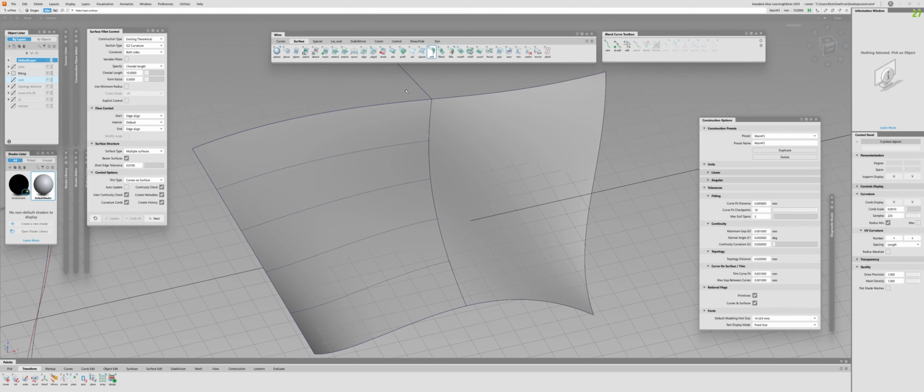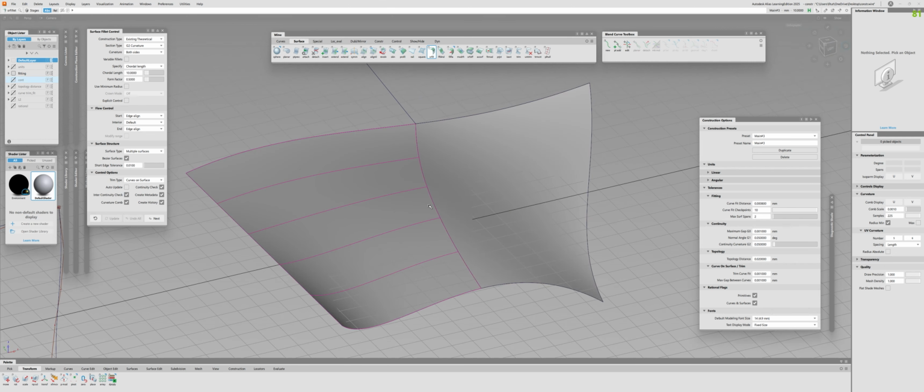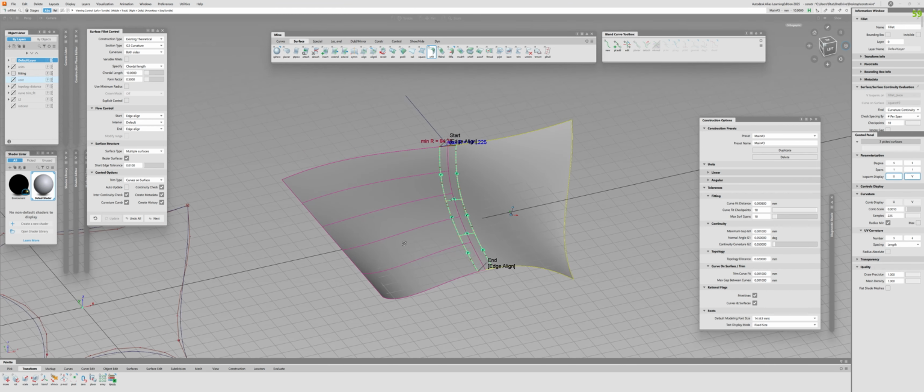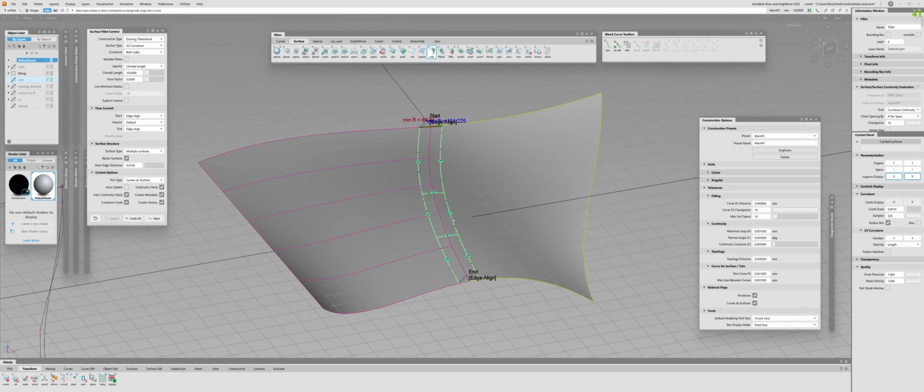Technically the same works for the Bezier surfaces, but the Bezier surfaces create separate surfaces, and you can use it as the quantity of the surfaces. So let me say that the maximum is 10, and it easily built me the transitional surface, the fillet with three surfaces. So we are within the max range. All right. And by the way, the curve fit distance comes into play as well.